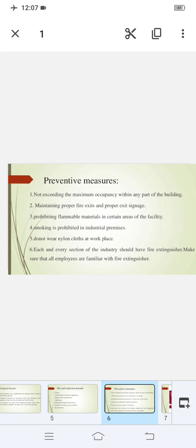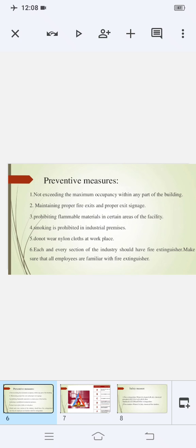Fire protection is an important part of good housekeeping, since a single fire or explosion can spread to adjoining units. Fire protection is applicable to the bulk drug industries, whether synthetic, biological, or microbiological. Government regulations are available for fire and safety protection. First of all, careful plant layout and judicious choice of constructional materials can reduce fire and explosion hazards. Hazardous operations should be isolated by conducting them in separate buildings. It will reduce the chances of catching fire.